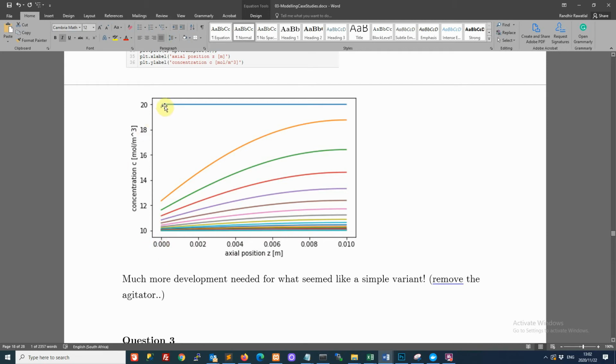Right next to the membrane, your concentration dropped initially, so that instead of 20 next to the membrane, the concentration went down, and you can see it kept going down until it reached the value across the membrane, which is 10. As the concentration was dropping near the membrane, component A was diffusing in to bridge that. From the bulk of the fluid, component A started diffusing towards the membrane.